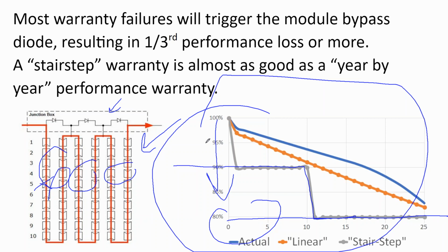It's not this like, oh, is this 97% with a 0.5% a year better than this other warranty issue. What triggers a warranty issue is you're looking at your array and one panel is not doing as well as the others. And sometimes that comes in during shipping. And so good installers are going to be checking their module circuit voltages on the install to make sure that everything's correct before they wrap up on site and call it a day.